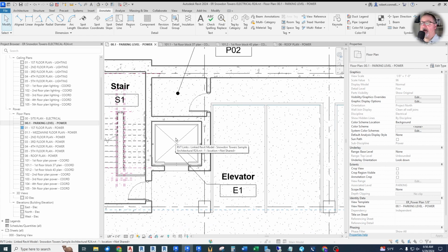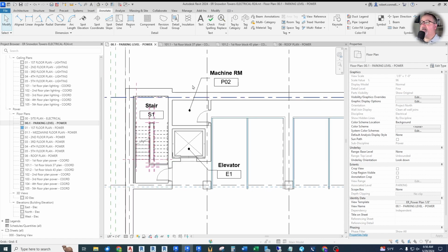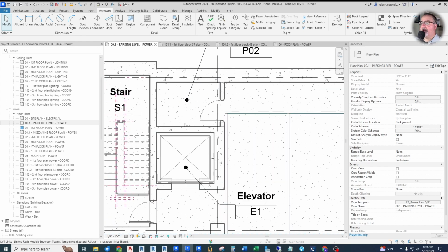To find out what you have for these various pieces of equipment, you can look at shop drawings or even catalog information from the vendors about what they need. You know, over the years, we've learned what elevators typically need, and it changes constantly. But the latest is when you have a separate machine room like this, they're going to have a 3-phase feed to the elevator motor, whether it's a hydraulic pump for a hydraulic elevator or whether it's a traction elevator and it's a 3-phase motor. But there's one big disconnect, usually fuse disconnect feed to this elevator. So I'm going to show that with a motor connection.